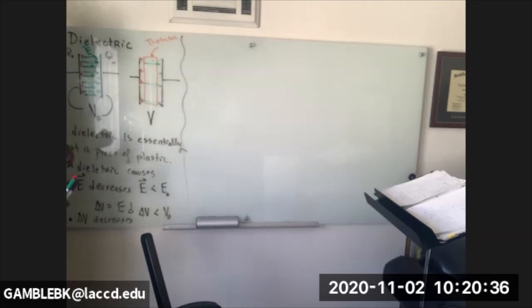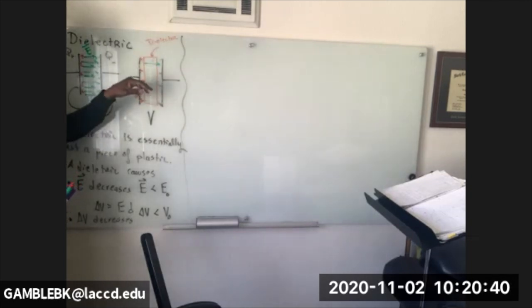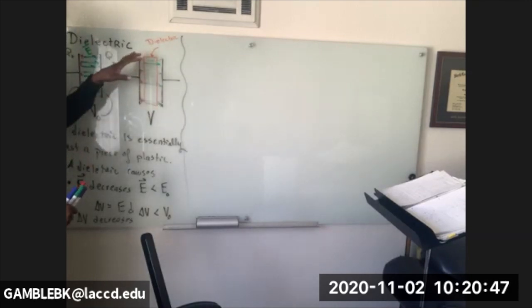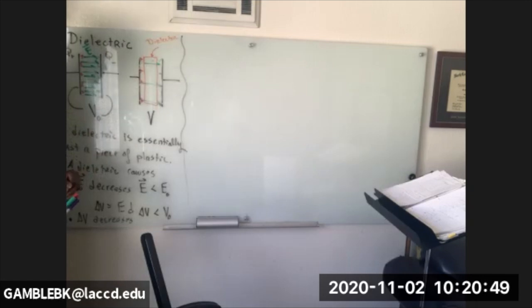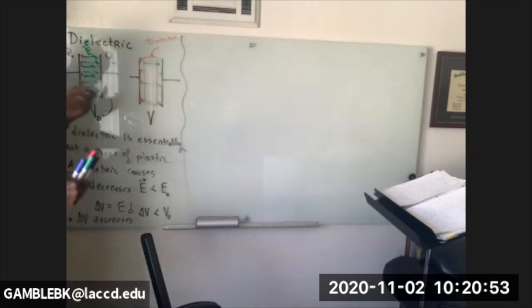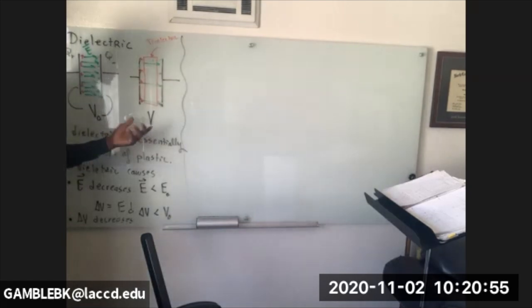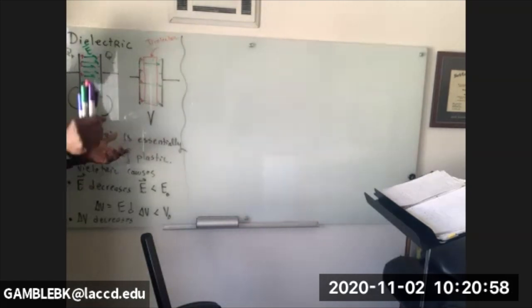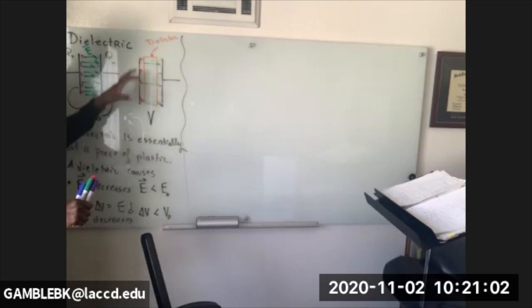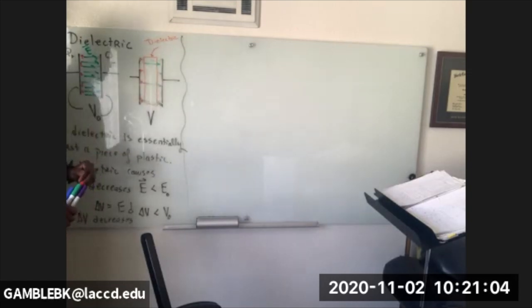although the field does diminish, which means that there must be another reason that the field diminishes in the dielectric, and it must have everything to do with the dielectric and nothing necessarily directly to do with the charge in the dielectric, because it does have charge, even though it's an insulator. It doesn't have any free charge, but it's definitely got charge, right? But nothing to do with the excess charge on the capacitor plate.